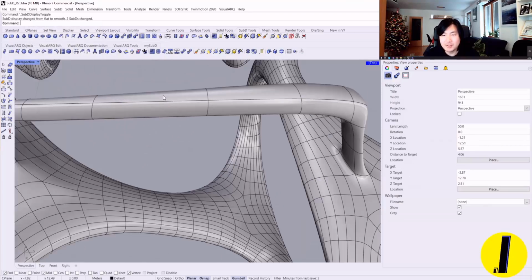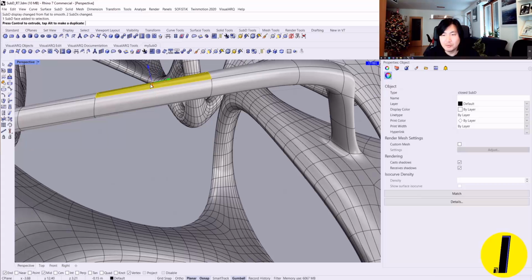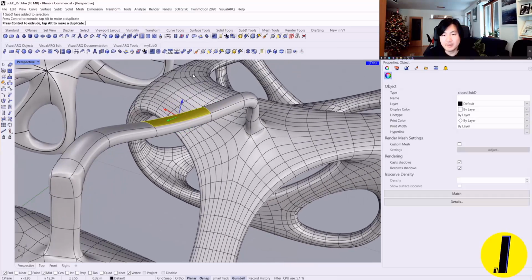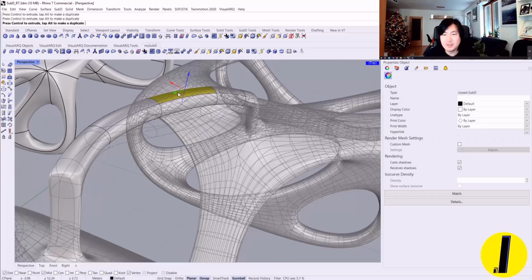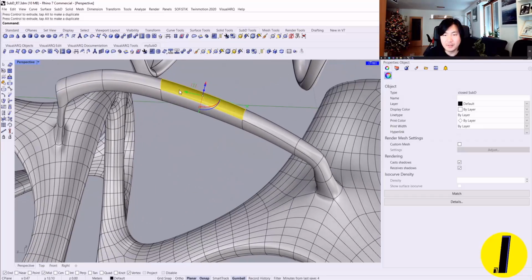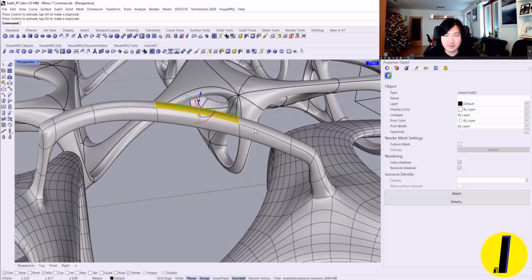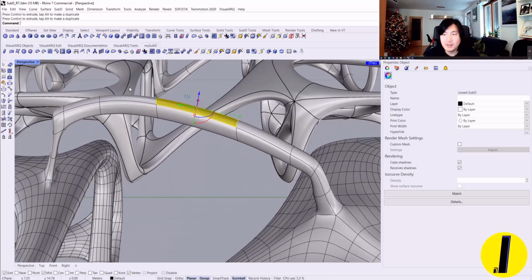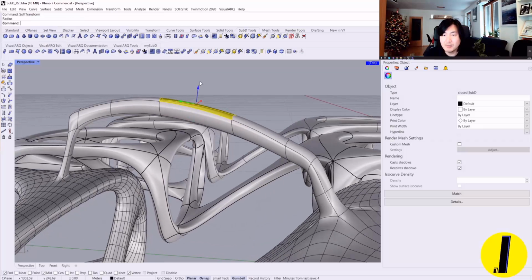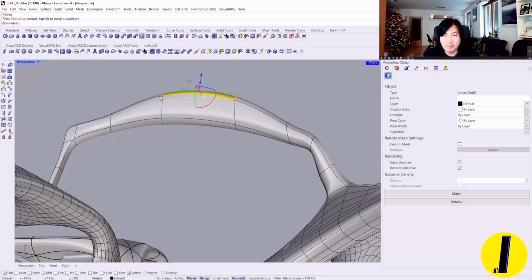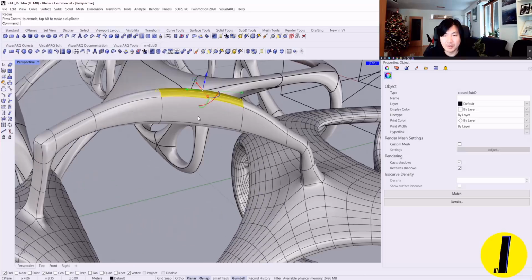It's funny. When you just select this one and move it, if I bring it out now, because the soft transform is applied, the whole adjacent faces are moving together. If I change this radius to smaller and move it now, as you can see, not the whole pipes are moving, only this area is extruding.